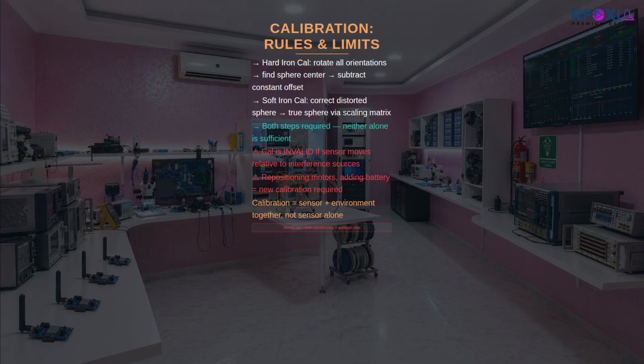For sensor fusion to work correctly, all three sensors must share the same physical reference frame. A module enforces that. Separate breakout boards assembled on a frame do not, at least not without careful mechanical alignment and measurement that almost nobody does.